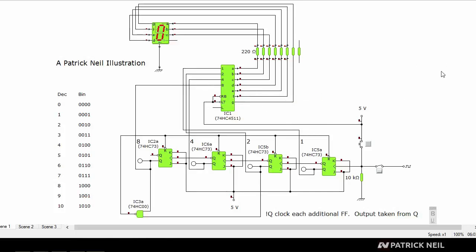Now, just as before, by using the output of one flip-flop to drive the input of the other, we can generate this sequence of signals here in binary. This circuit is a little different from the others because it resets itself whenever the code for 9 is present on the output.